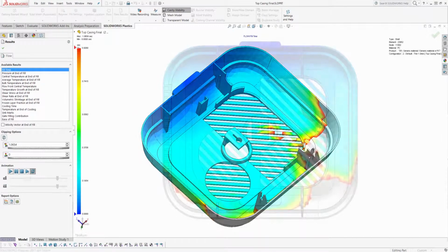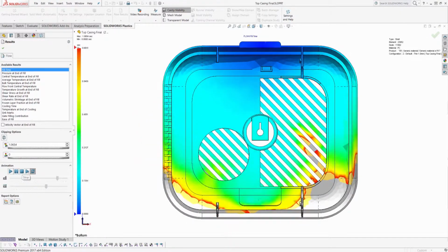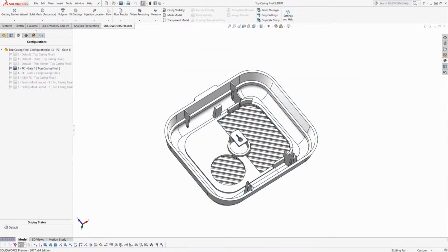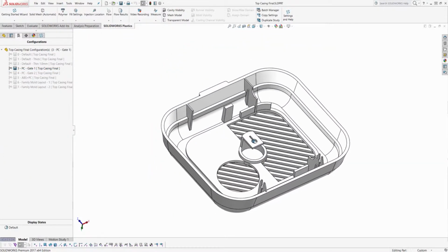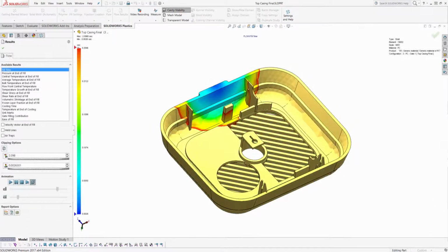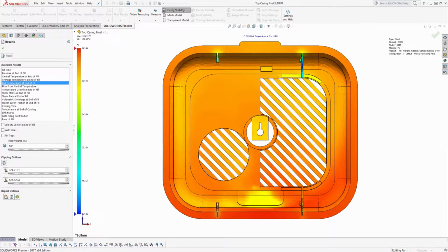Seems like the walls were too thin in this iteration and we have caused a short defect. A medium wall thickness is probably the best way to go for this model. This is a prime example of how a design problem can be solved within a few minutes versus a few days if we had sent it off to the manufacturing team.